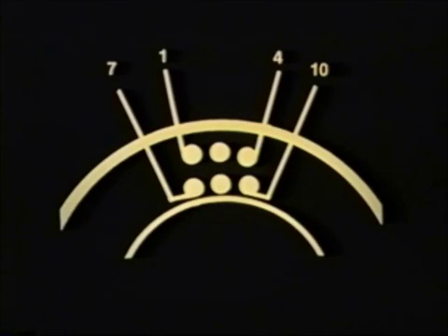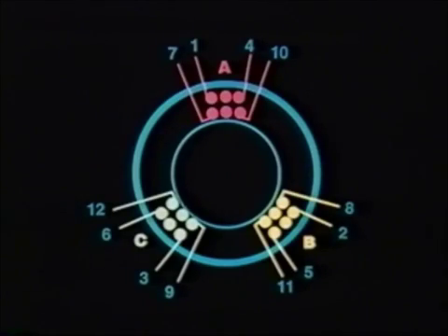To achieve two circuits, each phase coil group is split into two equal phase coil groups, and all four leads, 2 starts and 2 finishes per phase, or a total of 12 leads for all 3 phases, brought out to the connection box.